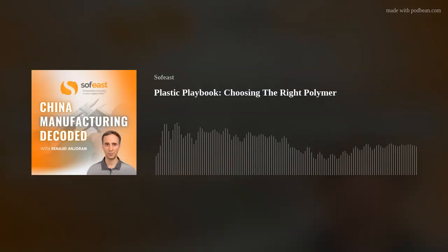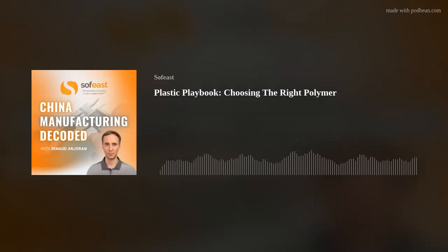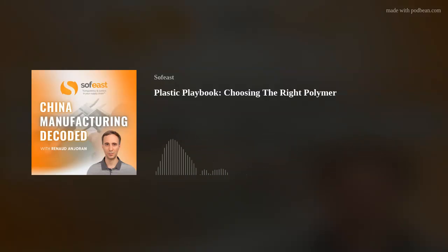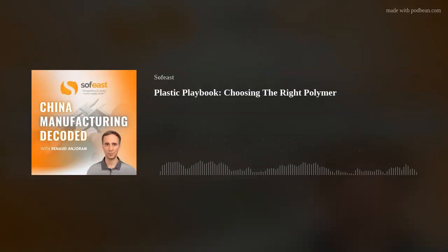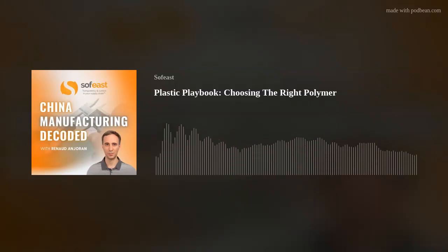What else have we got from a nylon? We've got some downsides, clearly. Now, nylon does absorb moisture, which can affect the dimensional properties of the product. So you've got to be careful there. So if you've got an assembly or sub-assembly, with a number of different nylon parts going together, that is used in an outdoor environment, in other words, susceptible to the weather and the climate, in other words, moisture gets in, you will expect dimensional changes on the products. And if that's a critical fit, you've got to be very, very careful.